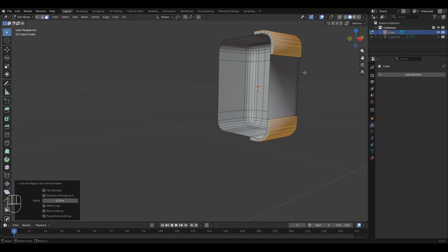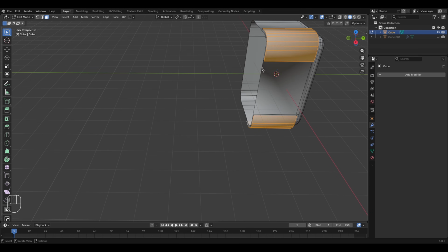After that, what I'll do is select the boundary edges on these details that we have created. In fact, let me select the required edges so that you can understand it in a better way. First I'll press 2 for the edge select mode. Then I'll select this edge over here.